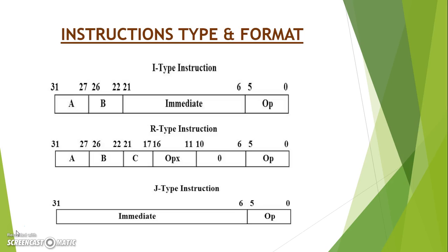A complete instruction set, including operand addressing methods, is often referred to as the instruction set architecture of a processor. The functional units of the NIOS II architecture form the foundations for the NIOS II. NIOS II has three instruction types: I-type, which is used for the load and store instructions, R-type, which is used for the arithmetic instructions, and J-type, which is used for the jump instructions.